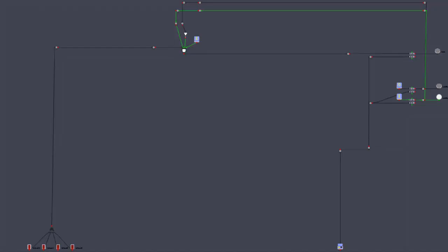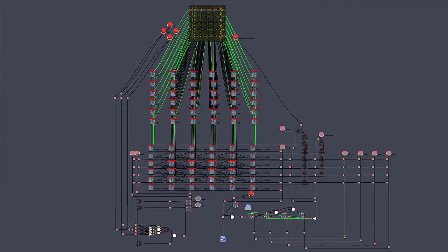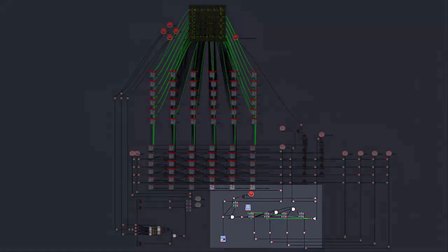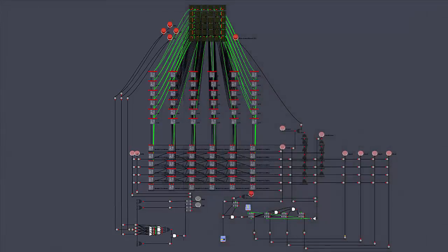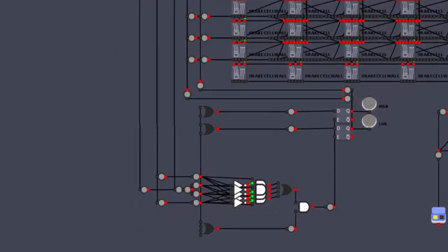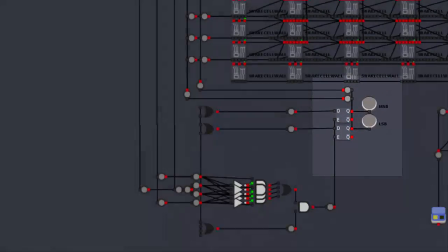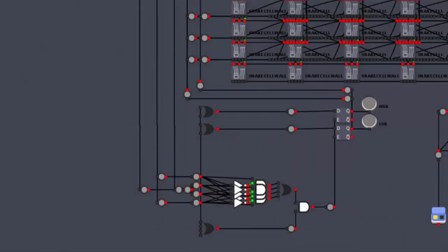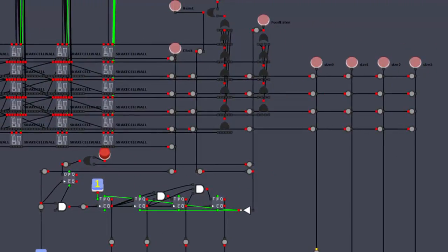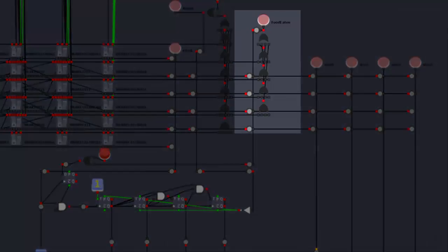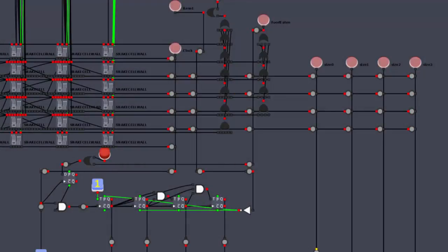Now that we have our cells working, they can be used to generate the final circuit. Beyond the snake cells and walls, the circuit must also contain a counter for the snake size and a form to send the directional input. The input directions are encoded and sent to a D latch, which is only enabled if a single direction is being pressed. The counter of the snake size is only incremented when the food has been eaten, with a delay to prevent collisions between the food being generated and the extra body cells.